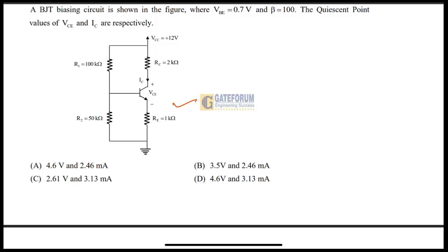for electrical, from the subject of analog. So here, if you analyze this circuit, this is a question based on biasing of the BJT by using the voltage divider bias. For this purpose, we can apply Thevenin to this part of the circuit, and then this part can be redrawn in this way.